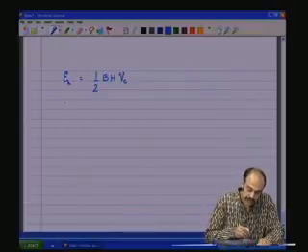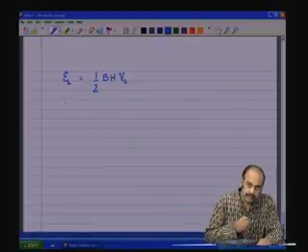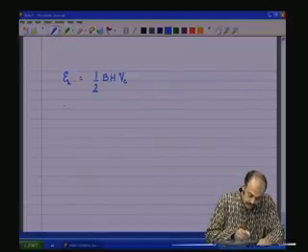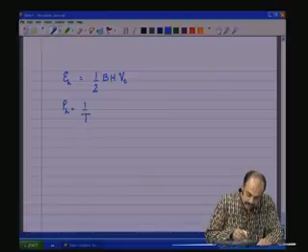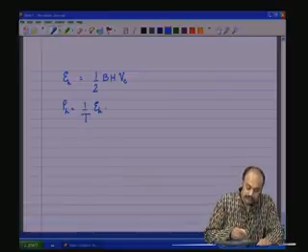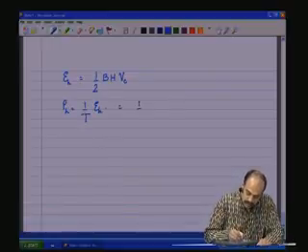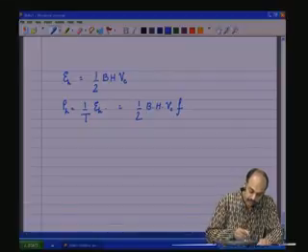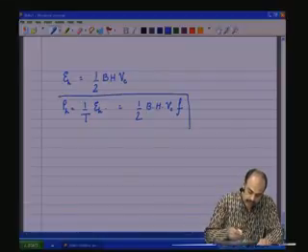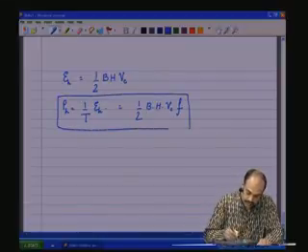Now, the power hysteresis loss is the rate of energy, which is divided by the period, one period. So, power is 1 by T EH, which is half BH Vc into f. So, this is the hysteresis loss equation.